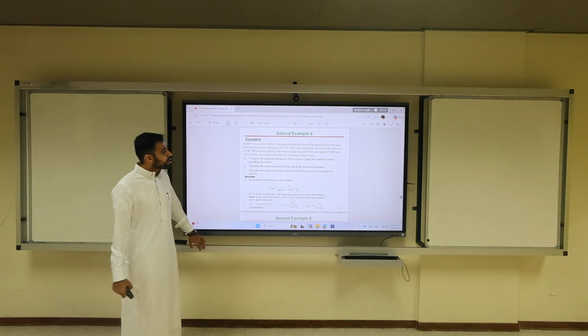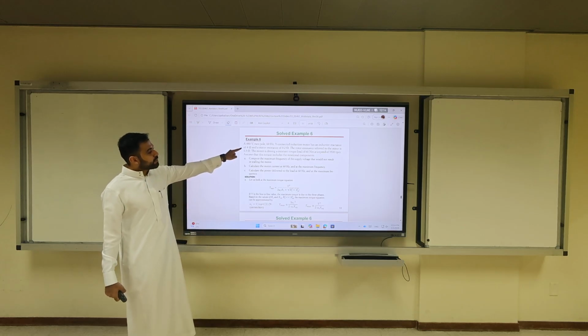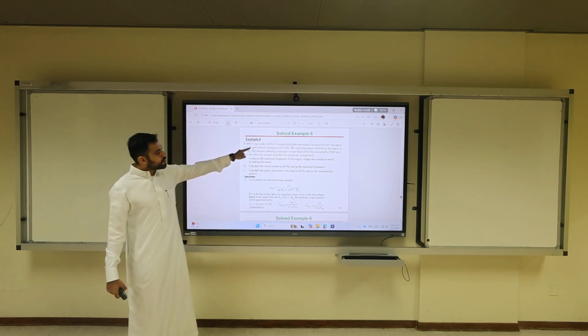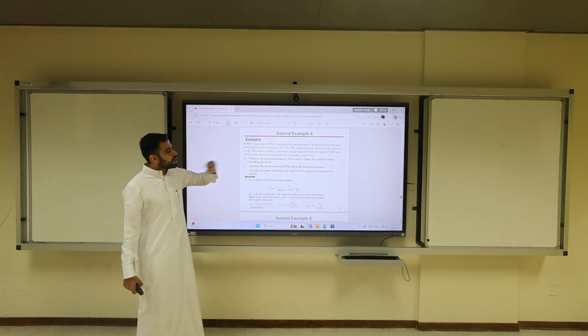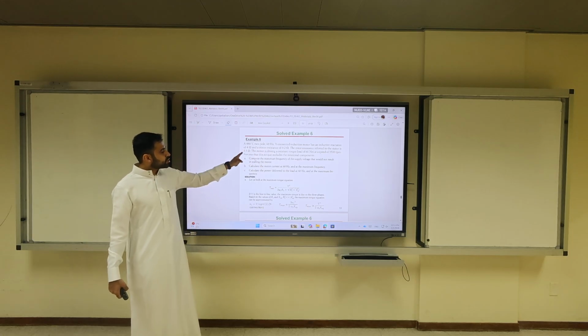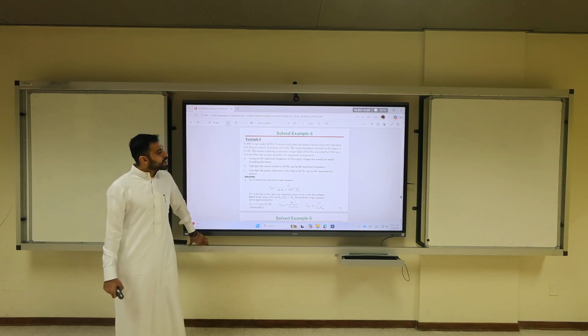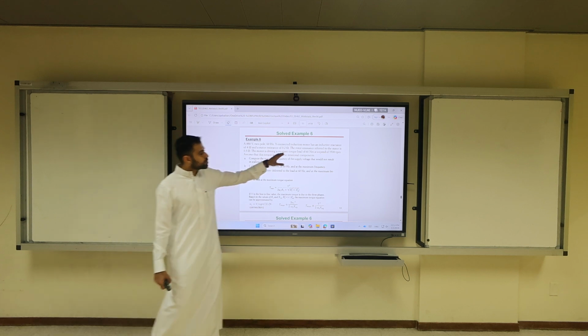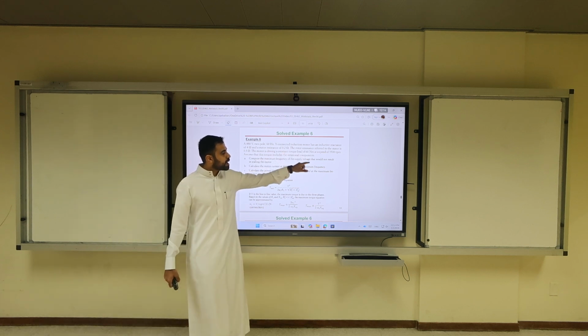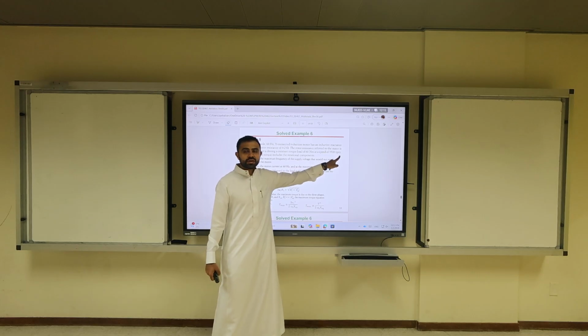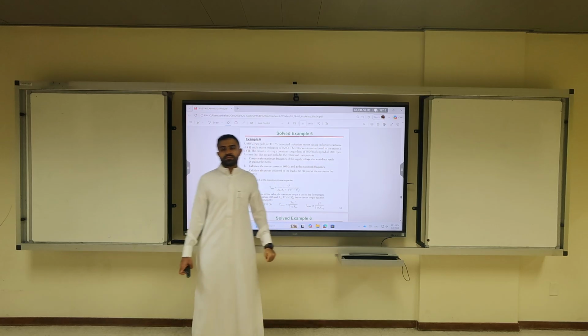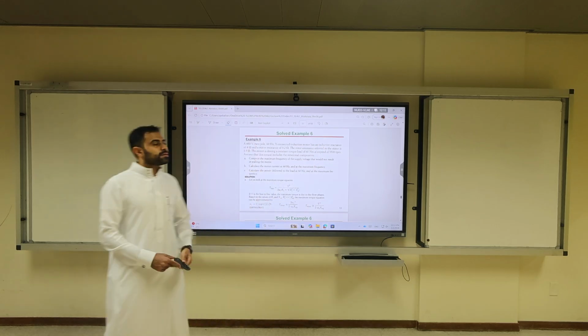Okay? And here what do we have? We have reactance of 4, resistance of 0.2. Okay? And another R, this is R1, R2 is 0.3. And this is X1. Okay? The motor is driving a constant torque load, so we operate at constant torque load of 60 Newton meter at speed 3500. What is this 3500? Is it synchronous speed or full load speed? Full load speed. This is a full load speed.